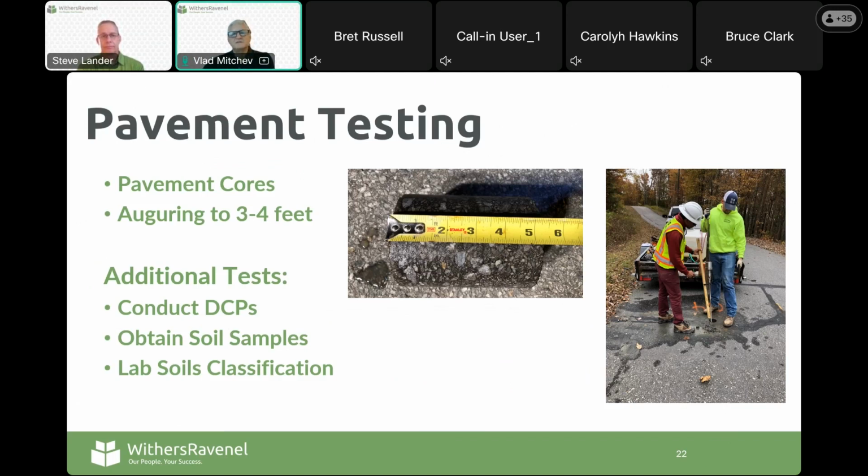Pavement thickness means asphalt thickness and base thickness and subgrade evaluation in terms of type, and sometimes you even need to evaluate strengths of the subgrade for larger projects, or if there are some issues currently. So pavement cores, when knowing the thickness of existing pavement in the resurfacing program, will first tell us how much we need to either mill, fill, or how much we have there.